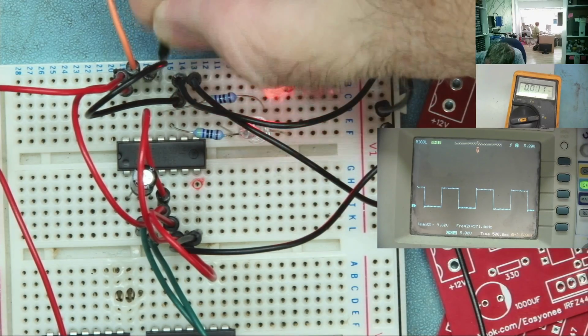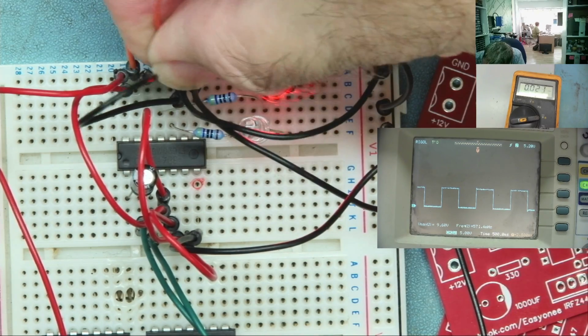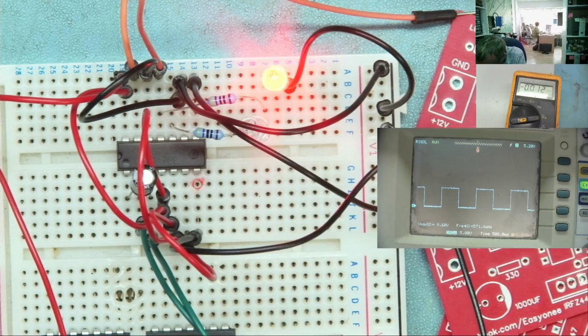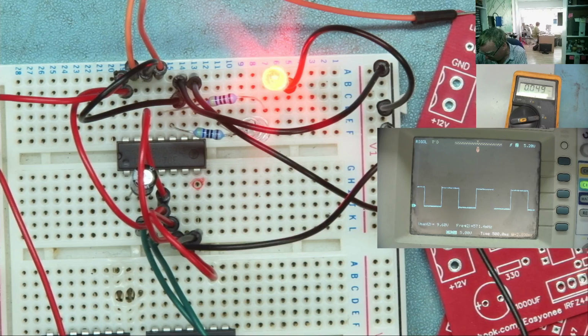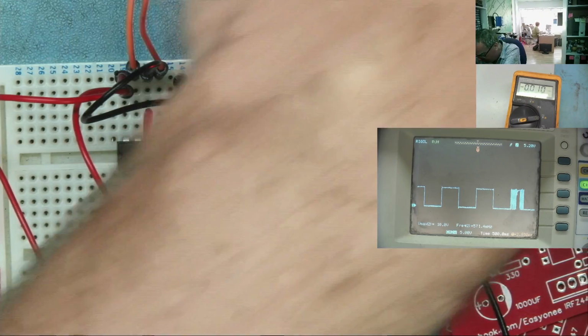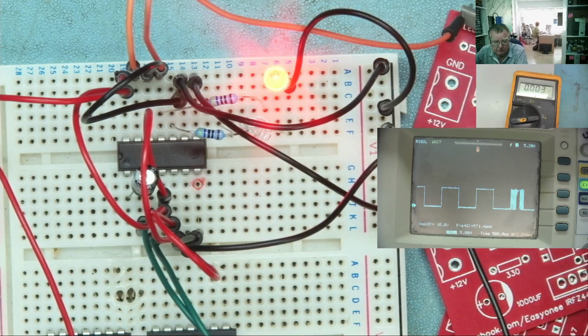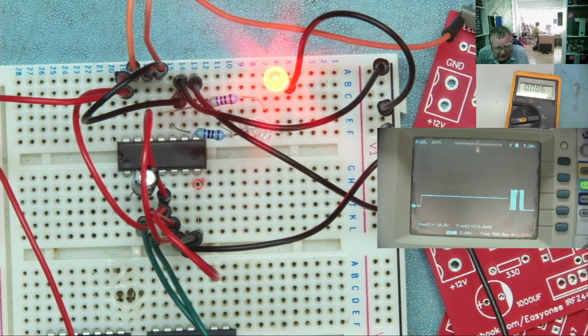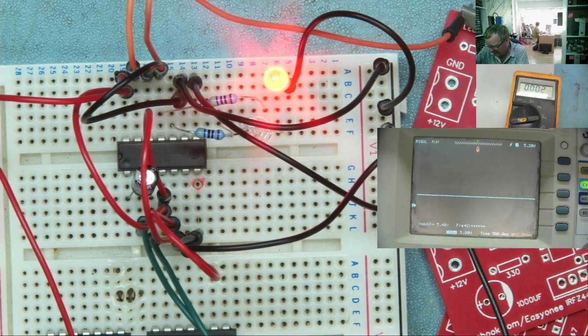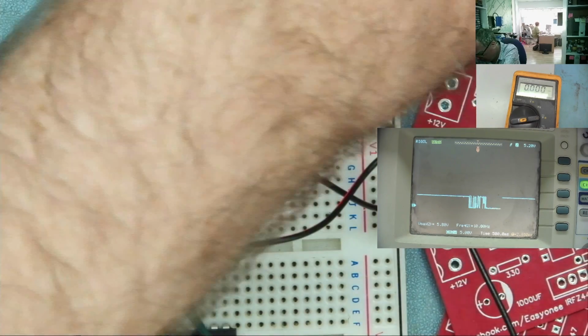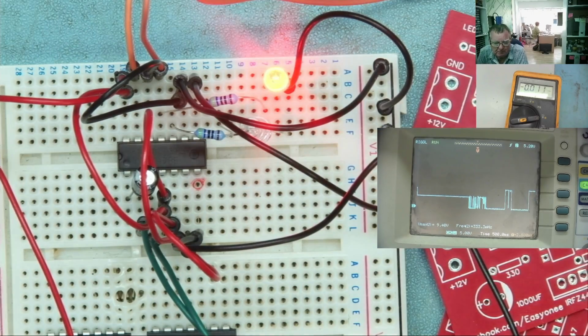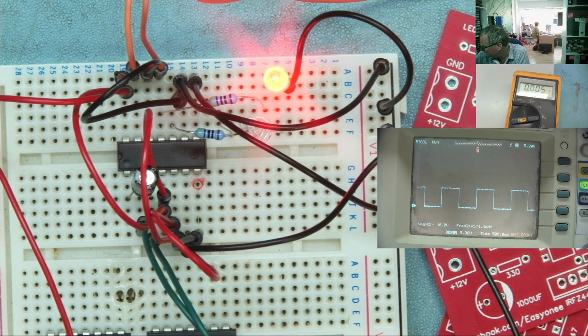I've connected another orange wire to the output which controls the LED, and we can see what's on there. And it's just high. We don't have any signal on there. Yeah, it's just high, 5.4 volts. Right. Connect back to the oscillating output on 13. And I'm going to take the voltage down now. So these chips should run down to 3 volts. Let's have a look what happens.